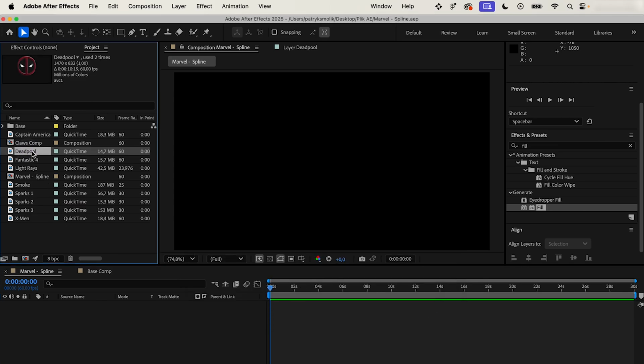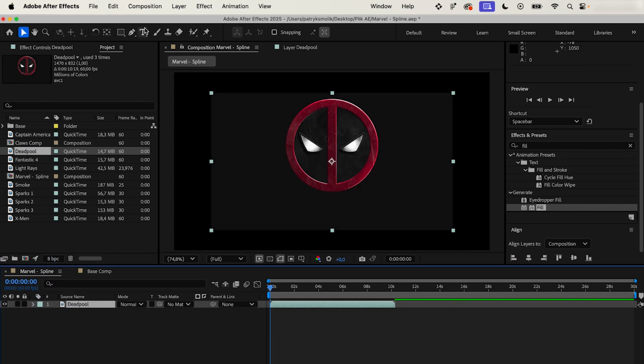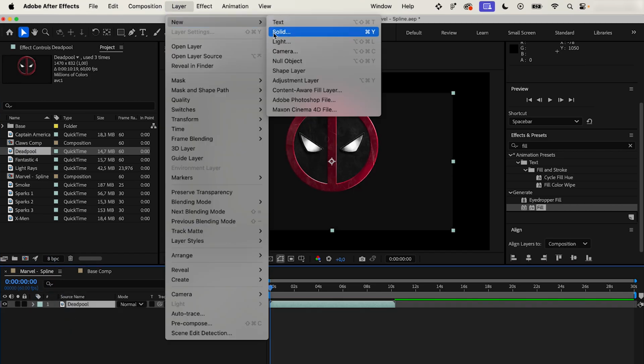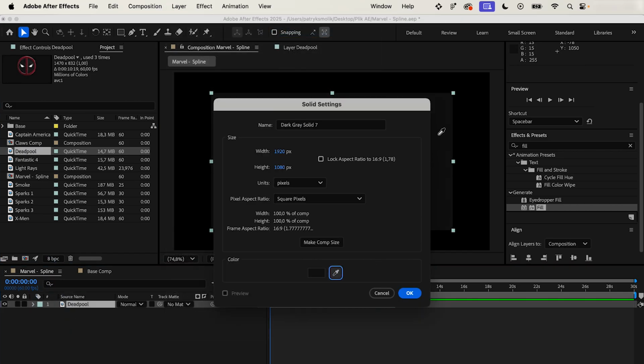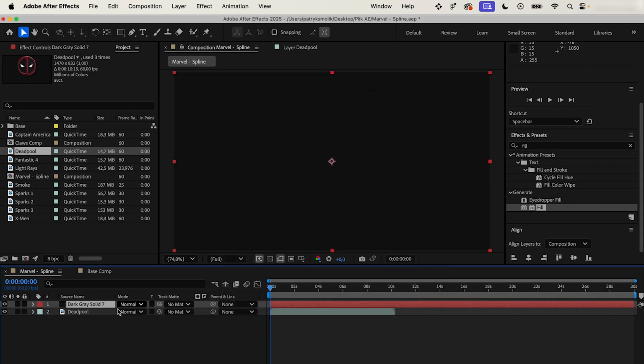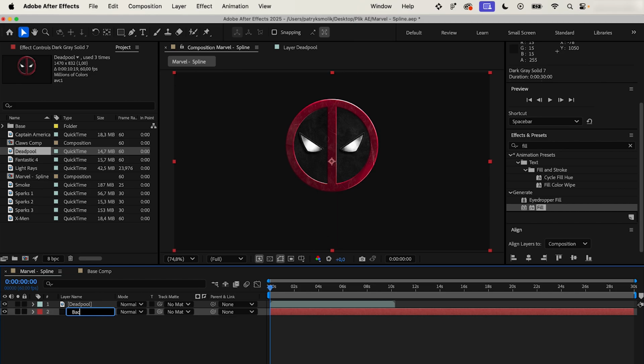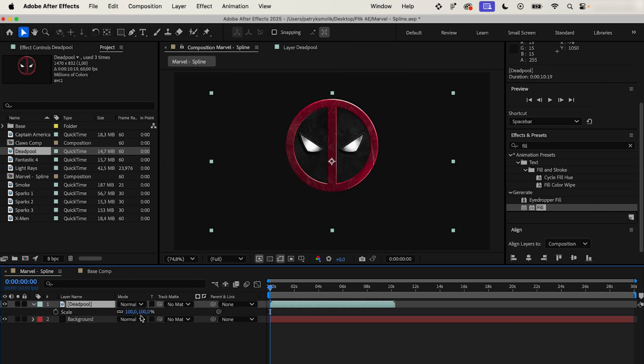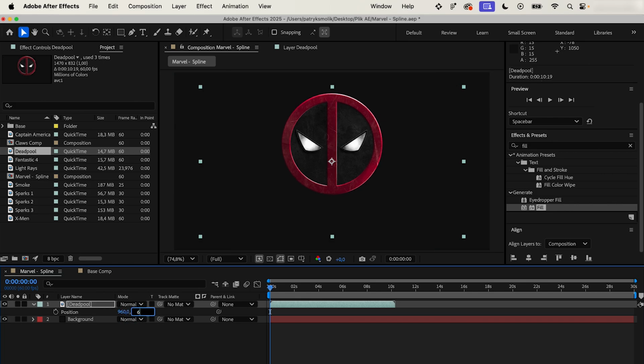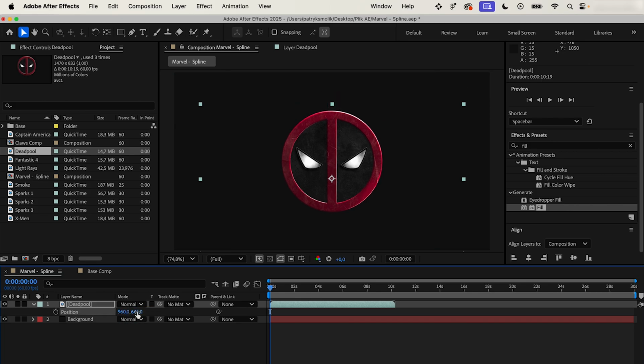Apply the first animation to the timeline. If you exported the files in MP4, as I did, create a new solid with the exact same color as the background of the rendered animation in Spline. Place this solid at the very bottom of all the layers. Adjust the position and scale to center the animation. You can use the proportional grid feature to help you verify the alignment.